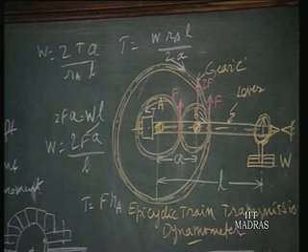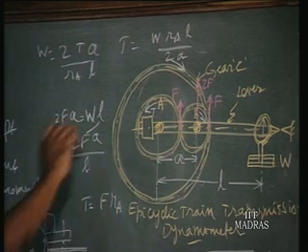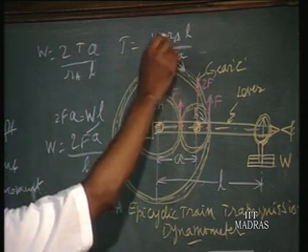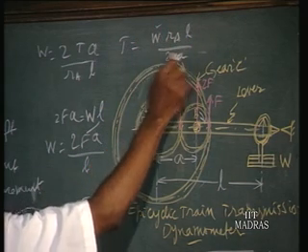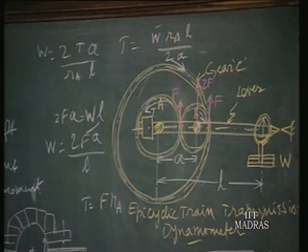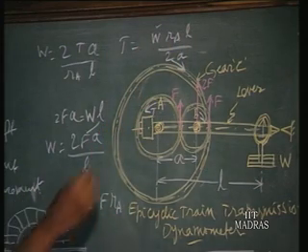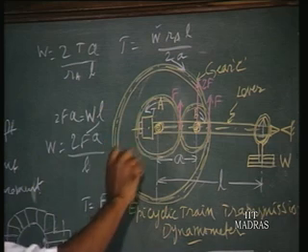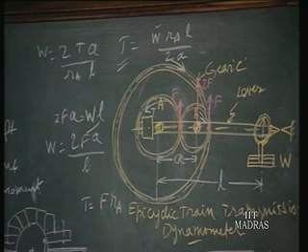So, this is the torque, that is F into RA. You can also have F, correct. So, in this except W, RA, L and 2A are all known. So, it is 2L W into RA. All the parameters except W are known, and that means by having different weights for different torque, we are measuring the torque. This is the principle of measurement by epicyclic transmission dynamometer.